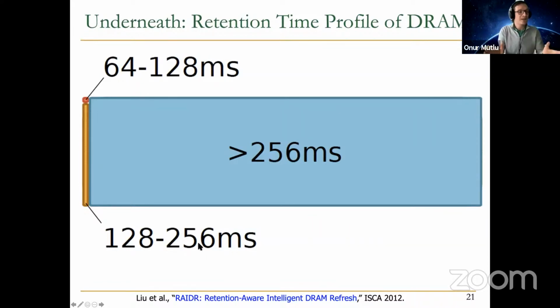Now, if you know this information or figure it out somehow, that's great. Then you can build a memory controller that dynamically adjusts the refresh rate based on which row these cells are in. So that's the idea, basically. That's the beauty of this, right? Now you have one more insight into the underlying circuitry and how it behaves.